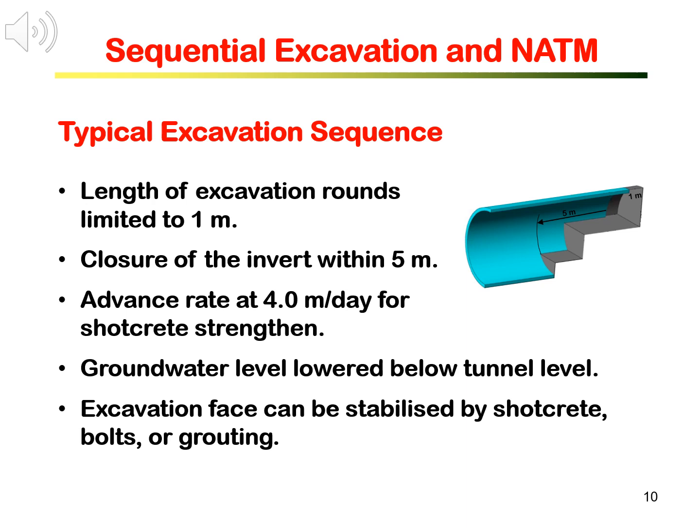Ground level must be lowered below the tunnel level. If in very poor ground, the excavation phase can be stabilized by shotcrete, glass fiber bolts, and pre-grouting, and so on.